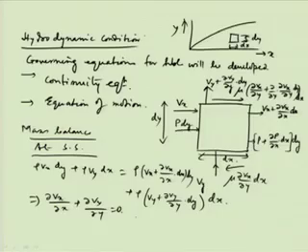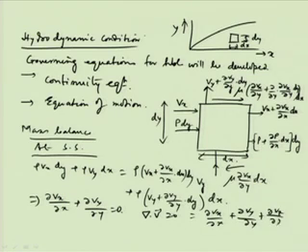So, we know the volumetric continuity equation, grad dot v equals 0; in fluid mechanics we have studied this. What does it say? It is del Vx by del x plus del Vy by del y plus del Vz by del z equal to 0. In the present case the z term is not there. So, therefore, these two are matching. So, this is the continuity equation that we could develop from there, which is basically fluid mechanics.